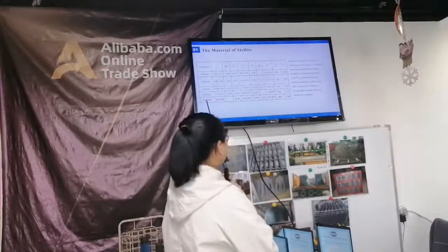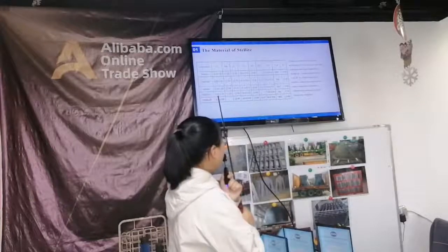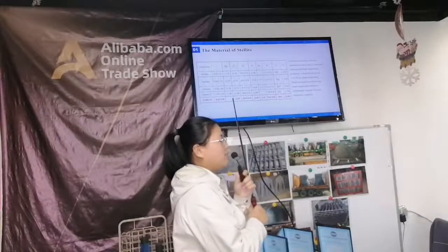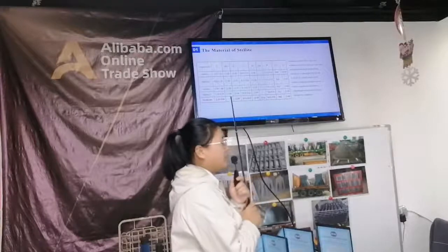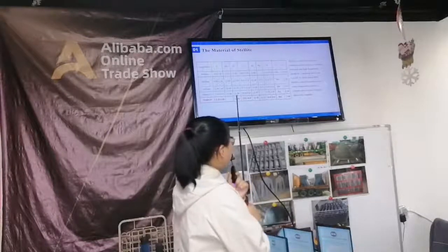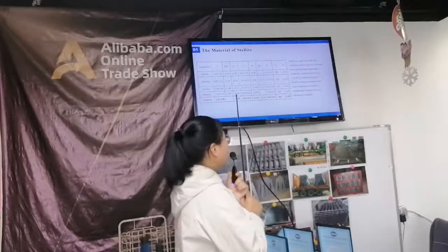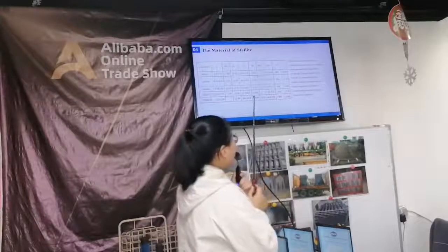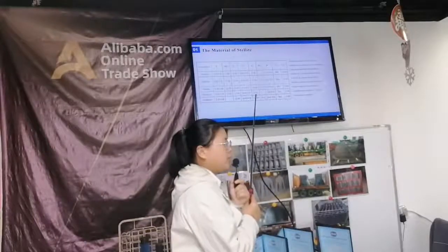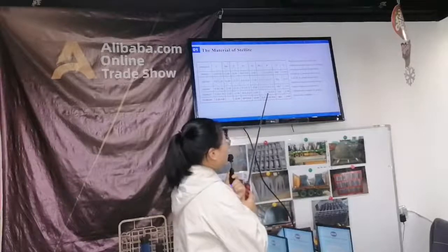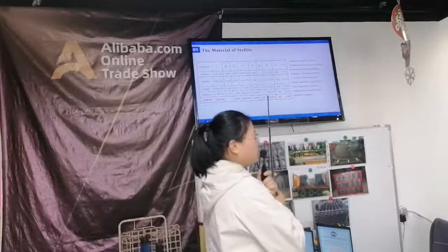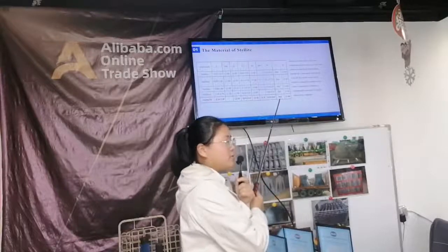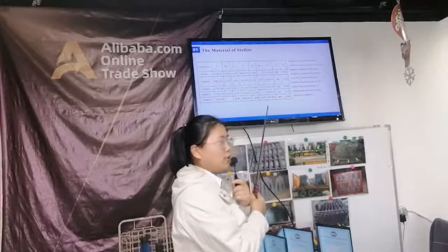Stellite 12: carbon is 1.1 to 1.7%. Manganese is less than 1.0%. Silicon is less than 1.0%. Chromium is 28 to 32%. Nickel is less than 3.0%. Tungsten is 7 to 9%. Iron is less than 3.0%, and the cobalt is balanced.